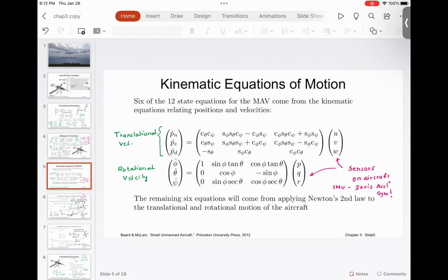And again, those equations are not difficult, but please understand a quaternion is a hyperplane. It's difficult for us to visualize. So even though we solve these equations in quaternions, when we try to visualize them, we convert those into Euler angles, because Euler angles are easier to plot or to visualize. Quaternions, even though they are elegant, don't have singularity, and are computationally efficient, are difficult to visualize because we can only visualize things in 3 dimensions.